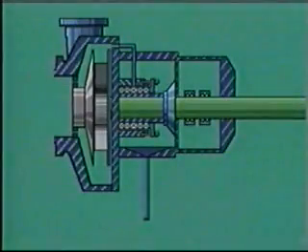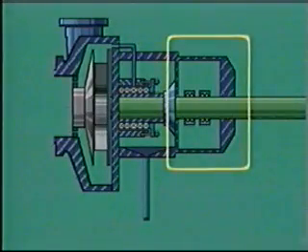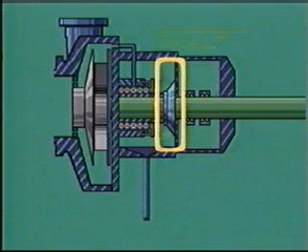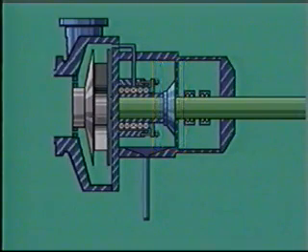These are bearing housings. They support and protect bearings. There are different types of bearings. We'll look at them and their purposes in section 3. Right here, next to the bearing housing, are flinger rings, or shields. They're attached to the pump shaft and fling fluid leakage from the packing gland away from the pump shaft. That keeps the fluid from leaking into the bearings.